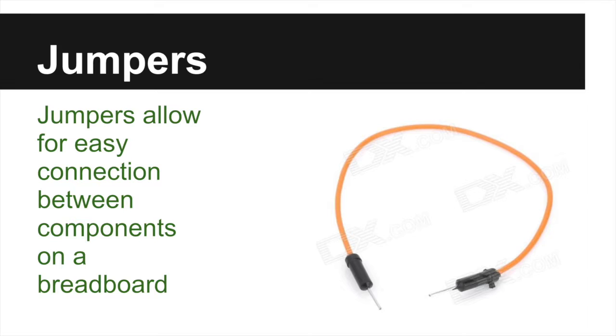If you've been color coding your wires the whole time, and you can tell them, hey, ground is green, red is power, and orange is signal, they're going to know exactly what to look for, and they're going to say, you have signal coming out of this place, but it really shouldn't be here. Move it to here. Or they could say, you have 5 volts going to this pin, but it shouldn't be here. Or, you forgot to ground this, all this kind of stuff. So they'll be able to help you as long as you have color-coded your circuits consistently. And that's why we went through that.